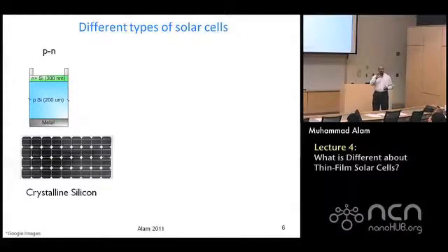And why is it 200 micron? Because it's a very weak absorber, indirect band gap. That's what crystalline silicon is. And so therefore it takes many, many bounces, on the order of 10,000 micron, before everything is absorbed. 50 bounces maybe before it's absorbed. So it's a thick material compared to what you could do with gallium arsenide or any other thin film technology.